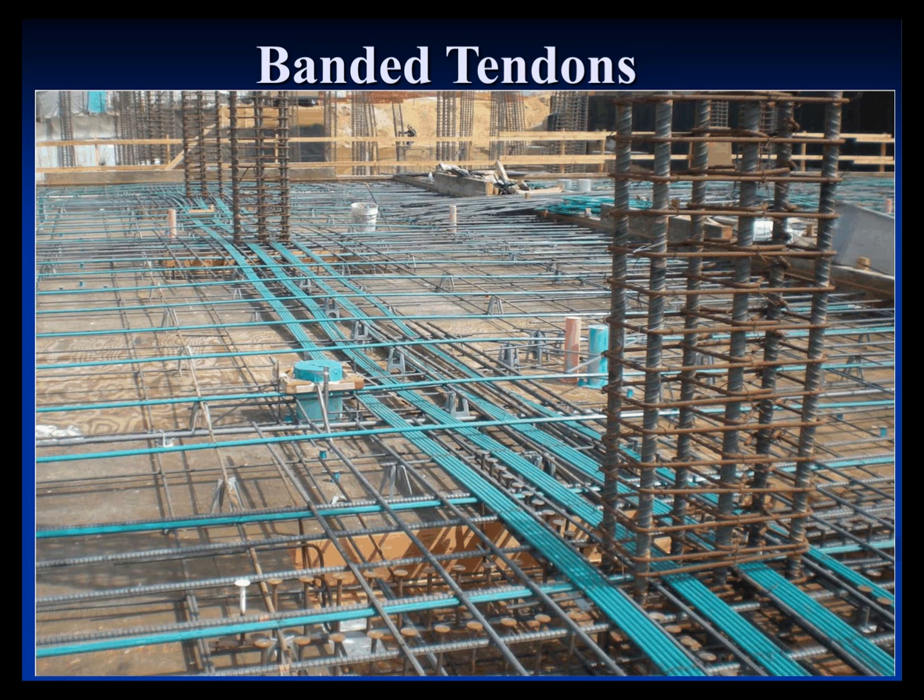which you can see here. Now, in the opposite direction of a two-way flat plate, you have the banded strands. I'm not going to get into the difference between a banded and a uniform in the numerical sense. It's purely a construction issue. You design the slab the same way in both directions, but you group them differently in one direction versus the perpendicular direction solely for constructability. So basically the same aspect applies. You're wanting to have a profile of the strands that are gradual, that hit the high points over the supports, meaning the columns, the walls, or the beams, and then a low point at mid-span to match your moment diagram and to match your design calculations.